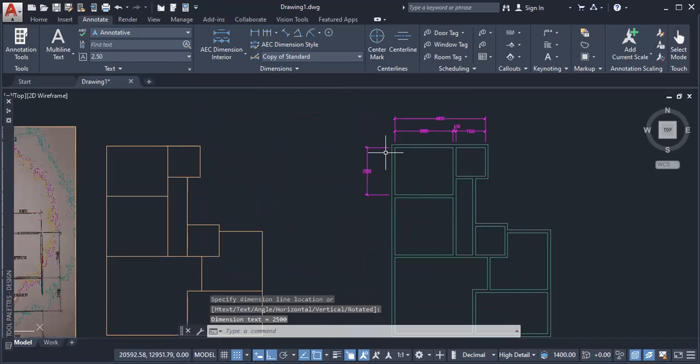It's important to realize the sequence when you're selecting the first one, if you intend to use continuous dimension. So we click here first, second point. The pattern will continue in the same direction. If I started here first and then click the second, the pattern will continue up. So it is important to start at the end and work in the direction that you want. Okay, so we click here, then click that point, click here, zoom in a little bit, click there.